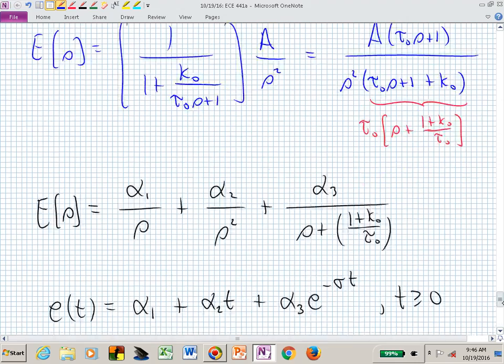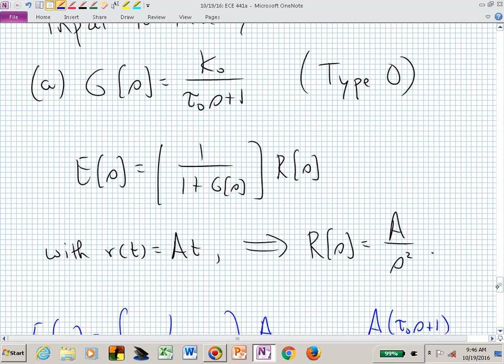So can you tell that by looking at the roots of the Routh-Hurwitz? You really can't, because it depends on what you're looking at. In the Routh-Hurwitz, if you were looking at the poles of your closed loop denominator, those might be stable. It's just that now your system, even though it's stable, is trying to get there, but it can't keep up with what you're asking it to do. The demands from your reference input signal are too much for this particular system type.